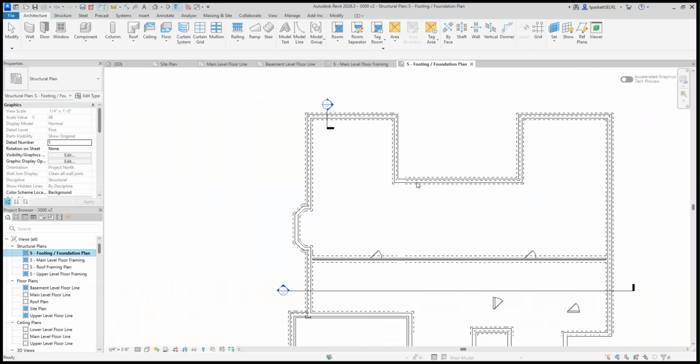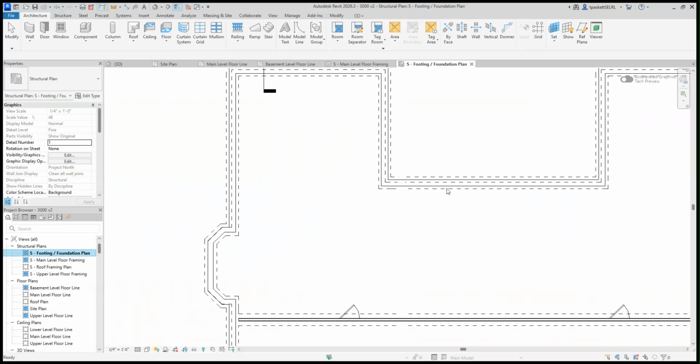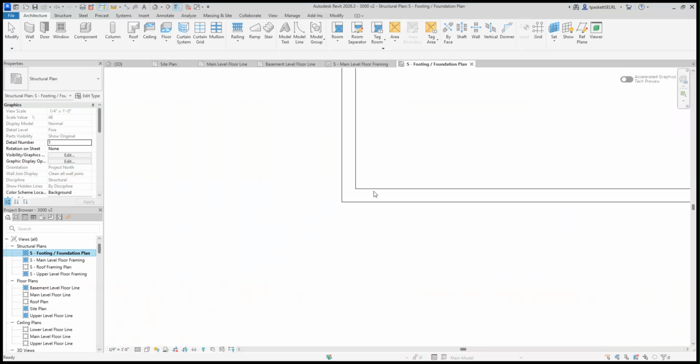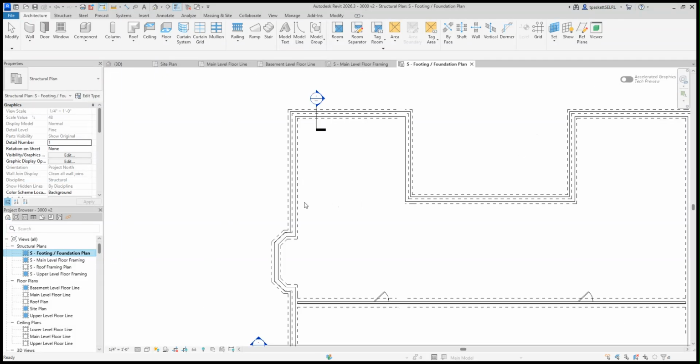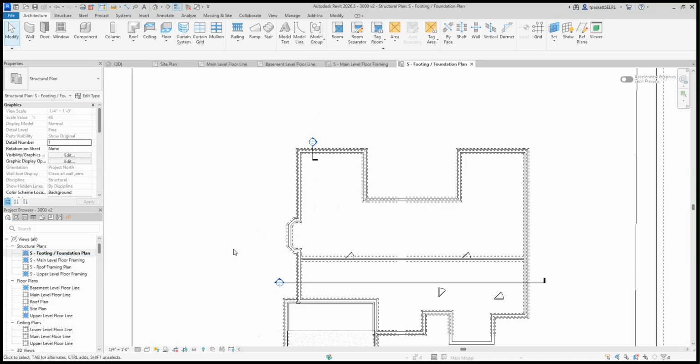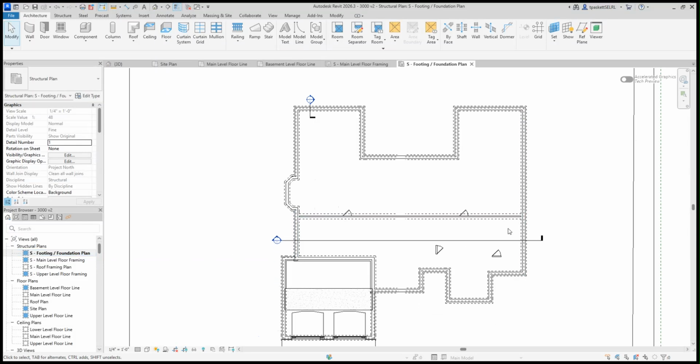We have our footings shown as hidden lines, and there's a little graphic glitch there, it looks like. But they go around and show things that are below our point of view. We place footings underneath the bearing wall here. We did not take care of the stairwell very well, and so we probably should come back and take care of that real quickly.